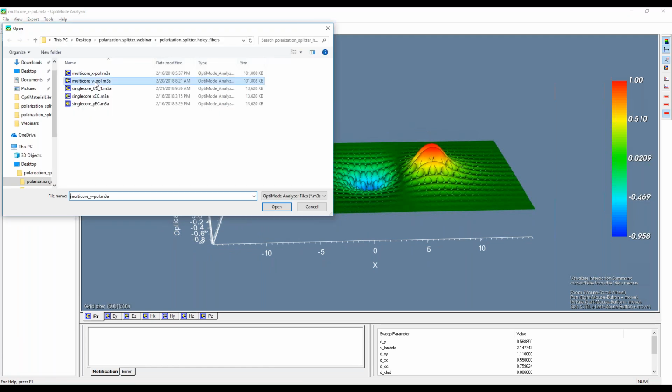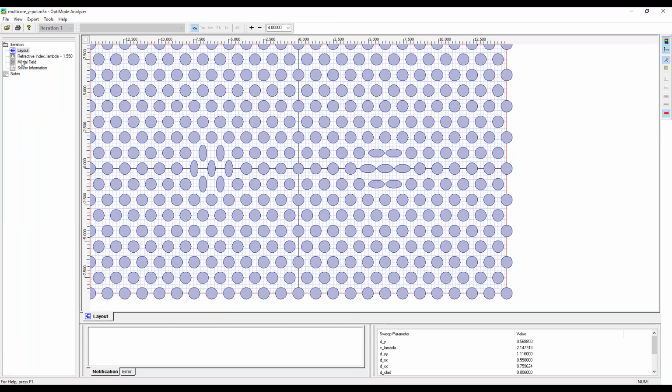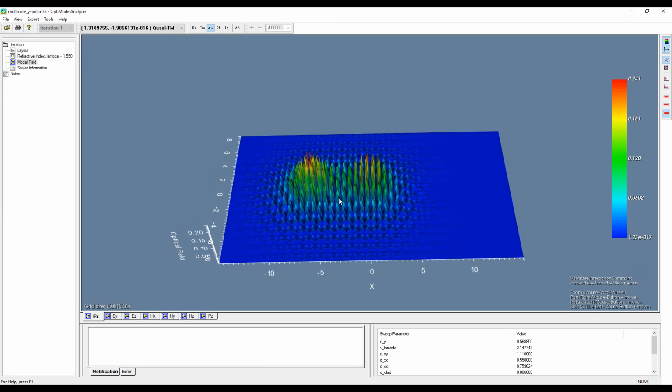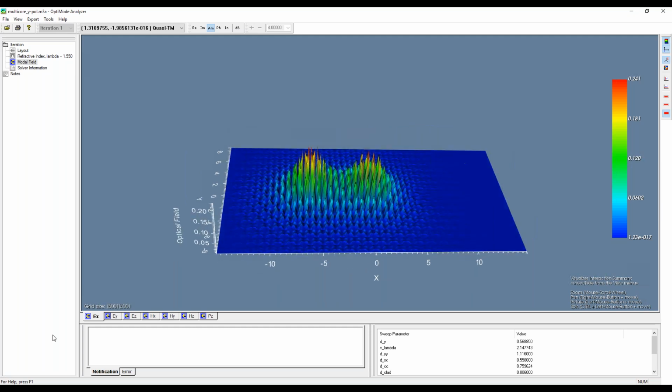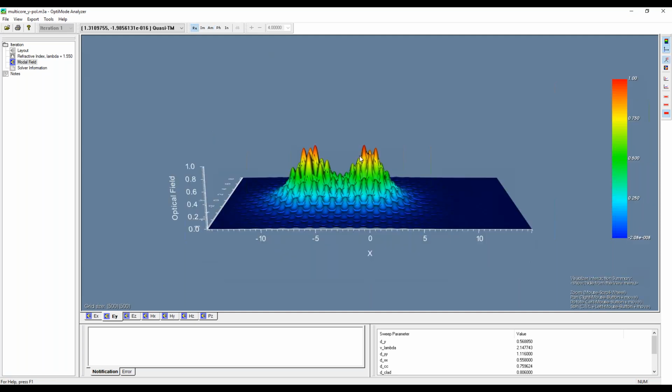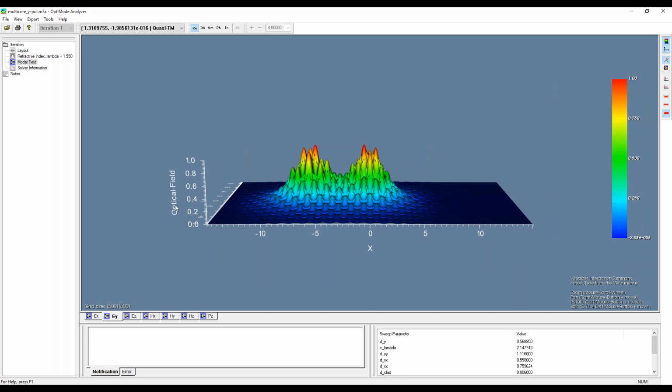I'll open up the y-polarized field mode structure. And look, this is the x-polarized, so you see that there's obviously some field in it, but the amplitude's much smaller than the EY, and the EY looks more clean because it's the dominant mode component. So again, for the EY, we have an even mode, and I'll just show it over like this to make it very clear. We have the even mode, and it's confined to the other 2 cores, the center core and the Y-designed core, and the x-polarized core is not really showing up in this picture.